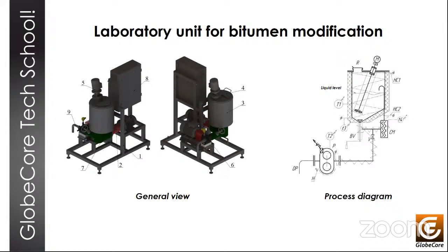The introduction of the additives requires the bitumen to be at a certain operating temperature, and that temperature is selected according to the polymer specification. So then, after a certain amount of time has elapsed for pre-mixing the components and the bitumen, the operator then can open the bottom valve. The valve itself has a rotating handle under the mixing vessel, and the operator turns on the mill by pressing the green mill button on the control cabinet.